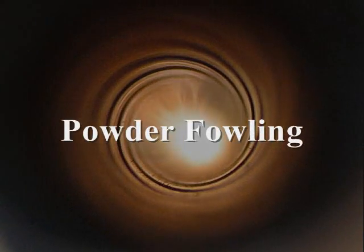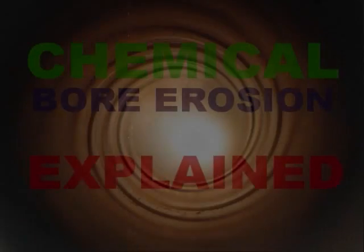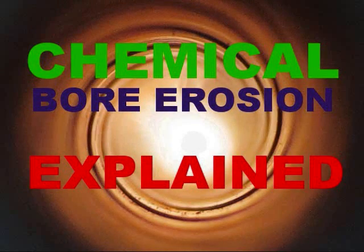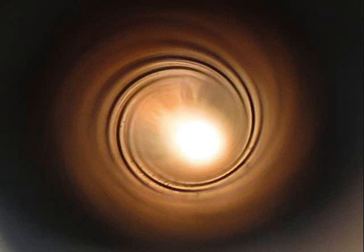Another thing that we're going to talk about is powder fouling, or propellant residue. Obviously, we talked about the chemical bore erosion mechanisms, because you have these different recipes of gunpowder, and some of the stuff in that gunpowder is corrosive. We talked about carbon monoxide, carbon dioxide, oxygen, all these other things, and nitrogen is actually kind of helpful. If you missed that, go check out our video on chemical bore erosion mechanisms. But in a nutshell, our propellant residue is also going to change the frictional dynamics of the bore, because if you have a bunch of gunpowder residue, each time you shoot, it's going to be distributed a little bit differently, and that's going to change your friction, which can also change your bore axis due to harmonic inconsistencies.